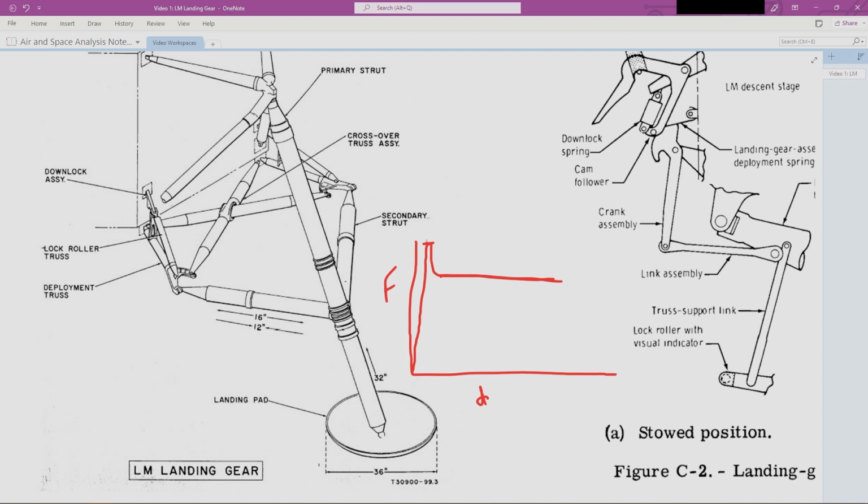This is just in the linear regime where there's no permanent damage in the honeycomb until it starts buckling, and then there is a drop in load typically associated with that. So what we're going to analyze is this peak right here. We're not going to worry about the honeycomb crushing, and even if we did, we would probably just do a static snapshot at some point rather than try to analyze the travel of the honeycomb.